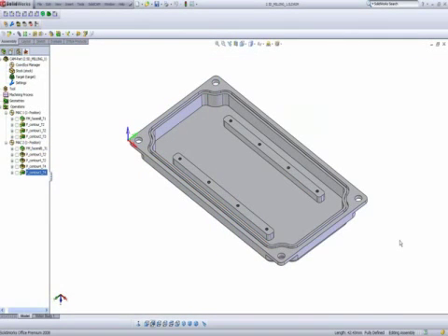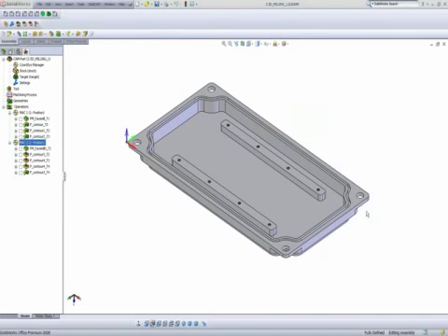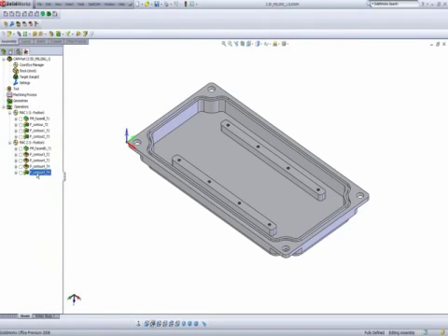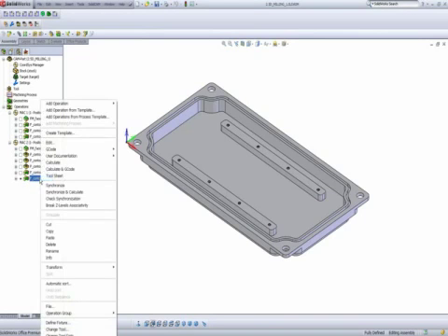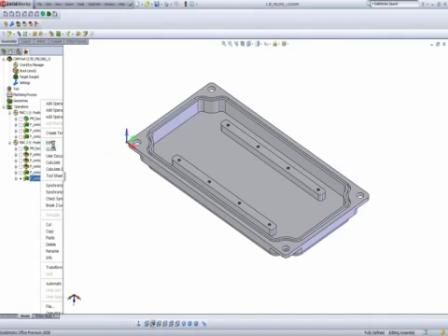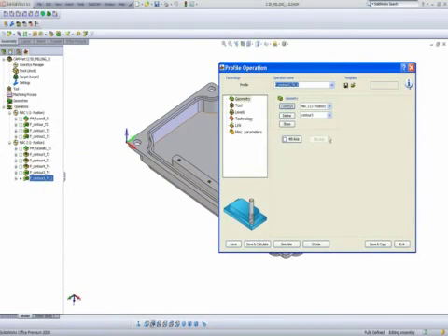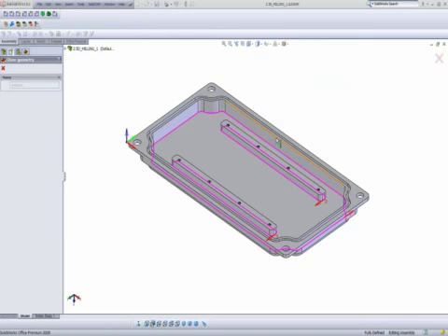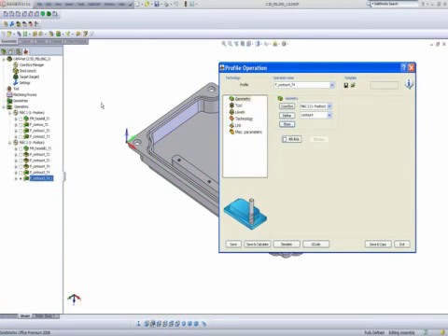that particular part. Now in my next operation, I'd like to finish off the walls of the island itself. What I'll do is I'll simply go into this particular operation that I've done before, and I'll say copy and then say paste, creating a new operation, and then just change some of the details. For example, I'll change the geometry that I've used. In this particular case, I'll change it to contour 4. But contour 4 is not really good because contour 4, as you can see, includes the outside geometry, which I do not need right now.